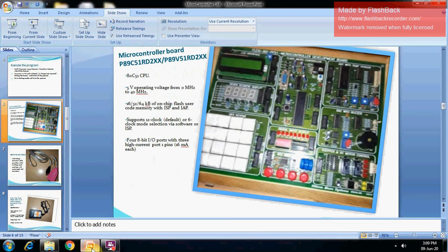For this, you can see here, this is the RS232 cable connector. So we need one connector, that is a USB to RS232 cable. That one we need, and also you need to give power to this board. For that we need a 9 volt adapter, and to interface this main module with other modules like the LED module or DAC interfacing, you need to use the FRC cable.